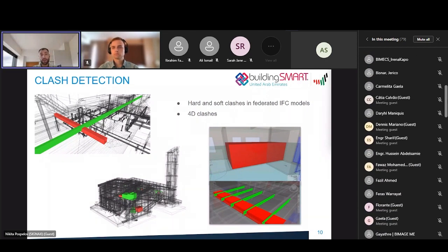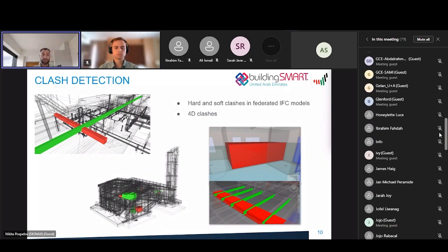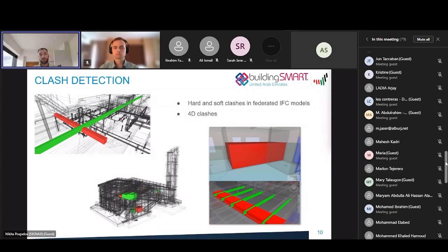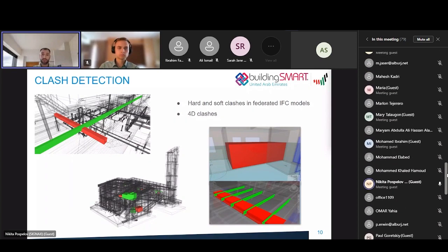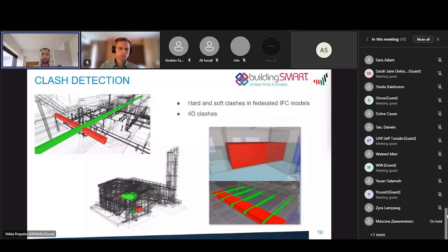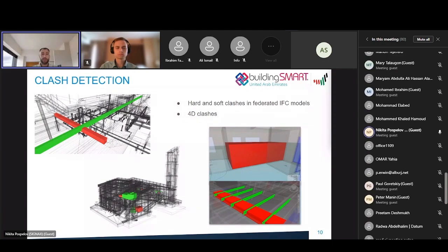By analyzing these clashes, our team was able to prioritize them based on their potential impact on the project schedule and budget. This helped us to focus our efforts on resolving critical issues first, while minimizing disruption to the overall construction process. Additionally, using IFC format for BIM model coordination helped us to ensure that all stakeholders have access to the most up-to-date information, reducing the risk of miscommunication and errors.